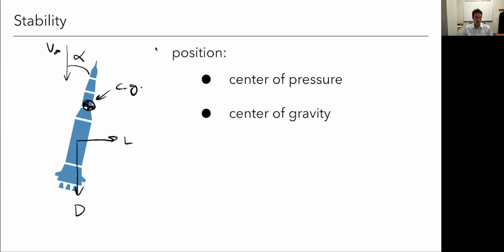The only slight difference in how you usually hear it is, remember, we spent a fair amount of time discussing the difference between aerodynamic center and center of pressure. Remember, the center of pressure wasn't super useful for us because it moves around as angle of attack changes. Whereas the aerodynamic center, by definition, doesn't move with angle of attack. So it was a nice reference point. For a rocket, the angle of attack is almost always going to be really close to 0.